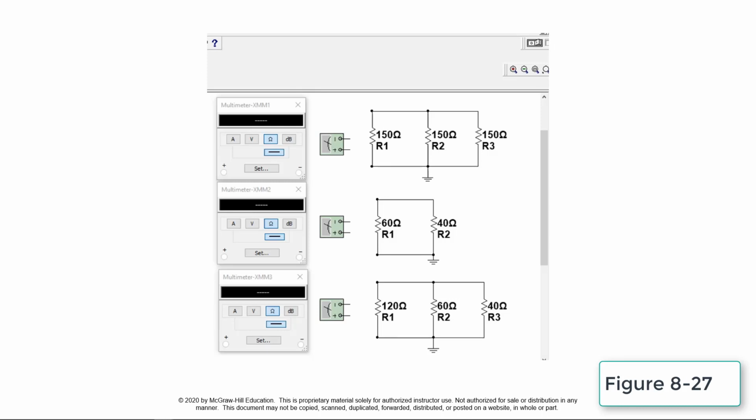This demonstrates the total resistance measurements of resistors connected in parallel. The resistors are joined side by side to form the parallel connection. The total resistance is always less than that of the lowest resistance present in any branch. Total resistance values can be calculated using equations based on the resistance value and number of resistors used.